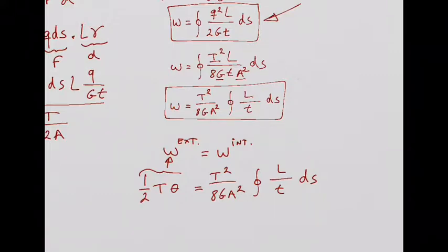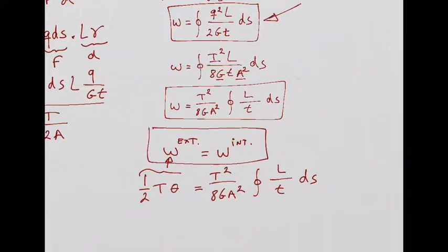Anyway, from energy balance, what this is saying is that when you apply, in this case, a torque, which is an external load, this torque will induce internal shear flows. So the energy produced by a torque needs to be in balance with the internal energy produced by those shear flows inside. So that's basically what we are saying here now, okay?